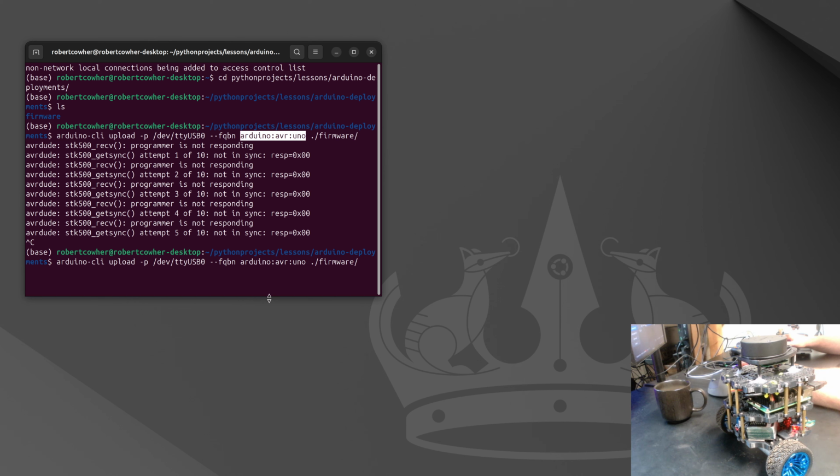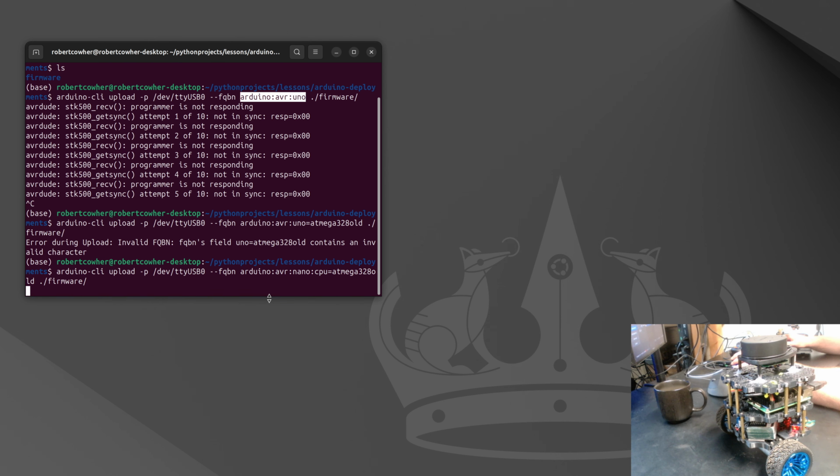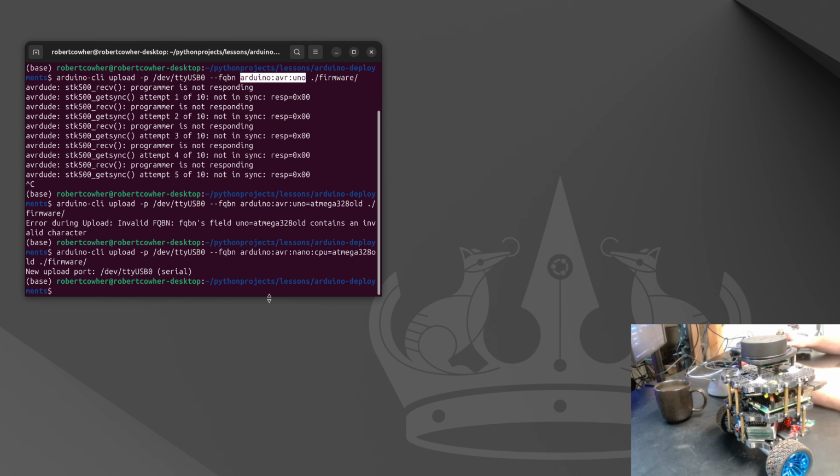So I'm going to do arduino:avr:nano:cpu=atmega328old. Let's see, what do we not like? I think I may need to, yeah, the nano part is kind of important too. All right, and that is actually a successful upload.